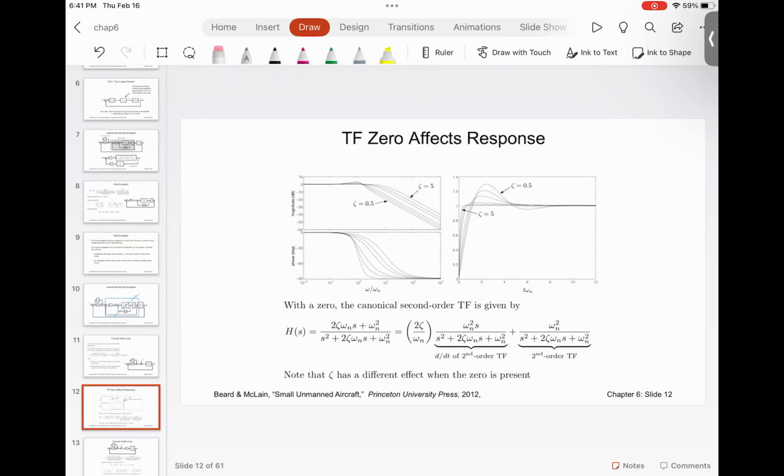And again, if you are a hardcore control theory or linear control systems person, then you can understand the issues of adding zeros in the transfer function, which is like adding a term that makes the numerator 0, or you can study the poles and do the root locus, all that type of analysis, and then try to tune the performance.